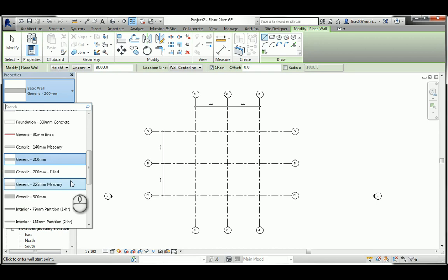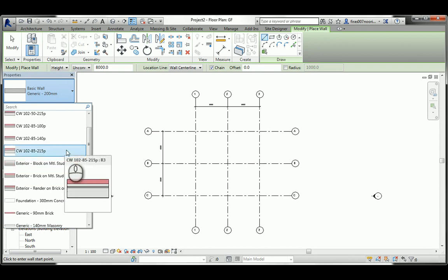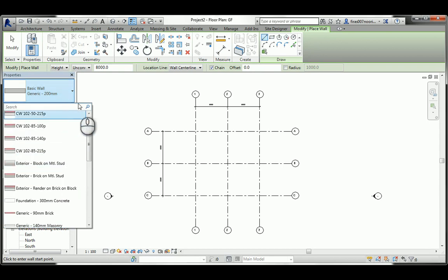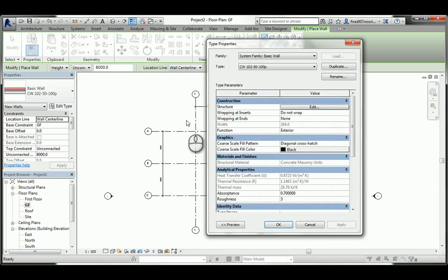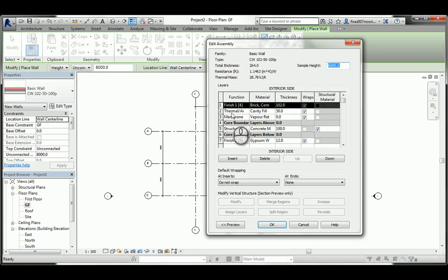It's a single material or a complex multi-layer of architectural components within the same wall. But again, you are not allowed to create a wall outside the project environment. So you have to take one of those and then change it. Just pick one of those, open it, go to edit type and see what types of materials have been provided.